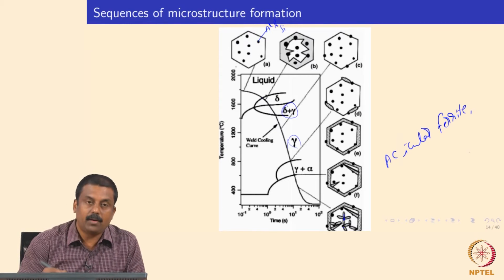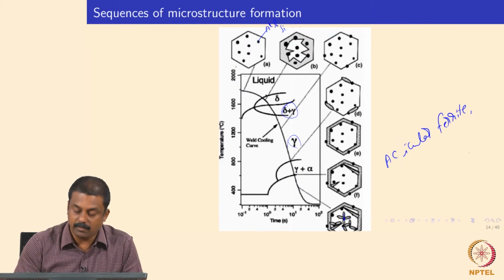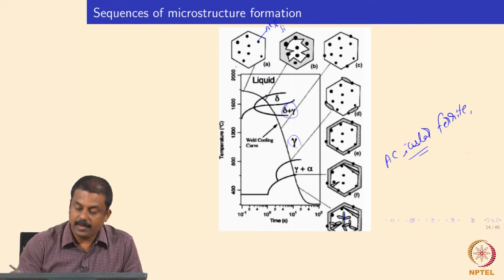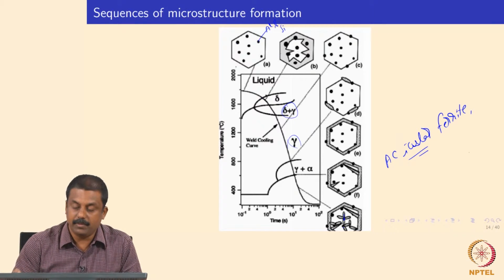If you carefully control the inclusion density, size and volume fraction, you may also promote the nucleation of acicular ferrite when the austenite is cooling to room temperature. The nucleation of acicular ferrite is seen as advantageous, because acicular ferrite gives the best toughened microstructure in terms of properties. Having an acicular ferritic microstructure is beneficial instead of having a fully martensitic microstructure.